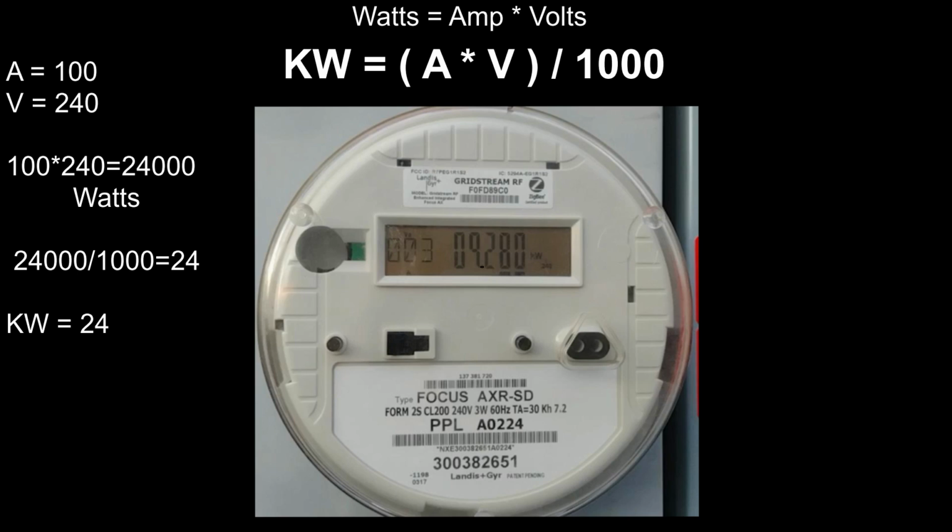Now that's what the system's maximum load is rated for. So with using the 80% rule, which means you don't want to load the system more than 80% of the capability as a safety margin, you should never see a number more than like 19 on that.